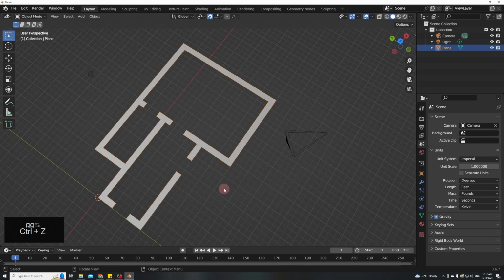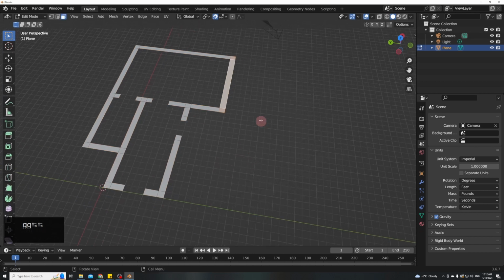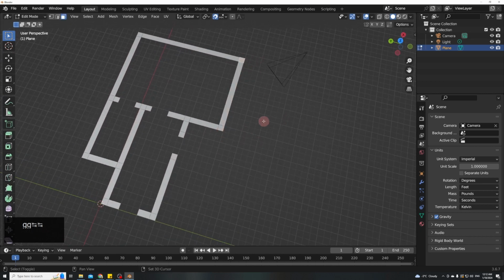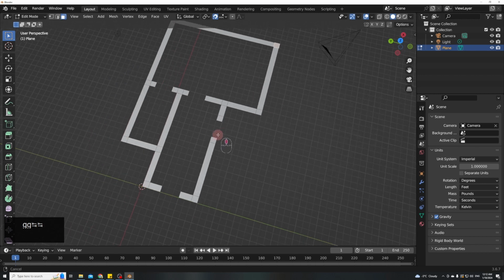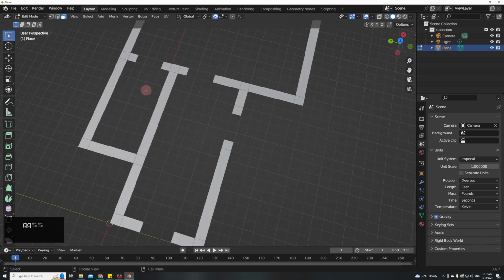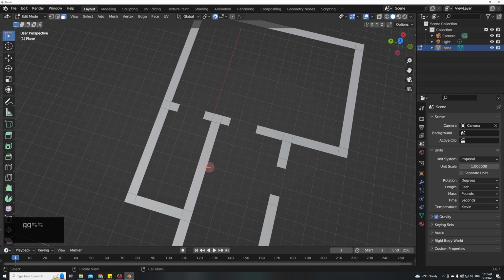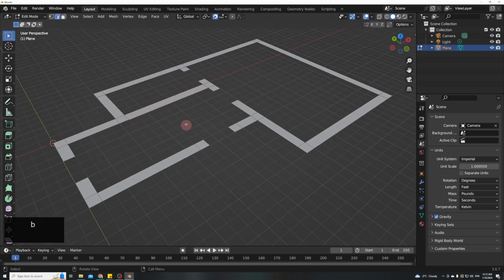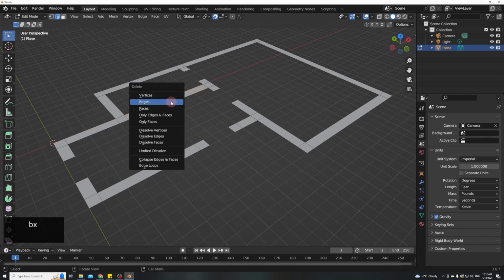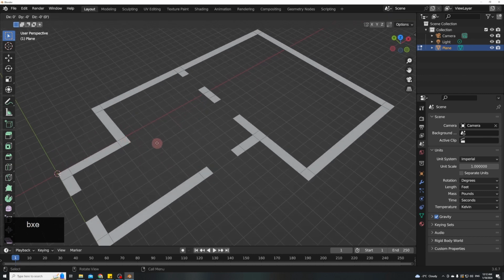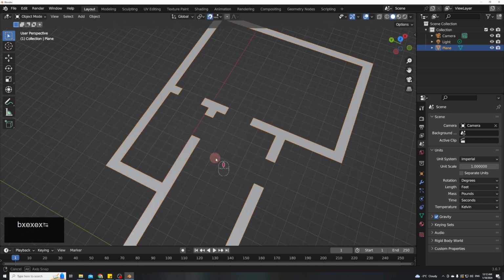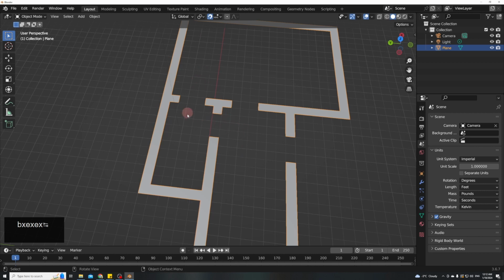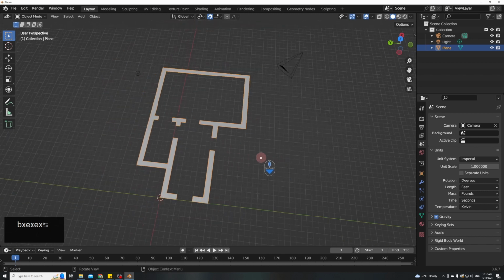I'm going to go ahead and finish by adding one more room, which is going to be the kitchen space. And I'm also going to add, like over here, I wanted another door into this bathroom. So what I need to do that, I'm going to select these 2 edges. I'm actually going to delete them. Then I select here, extrude X, and then extrude X. Now I have my extra door into that space.